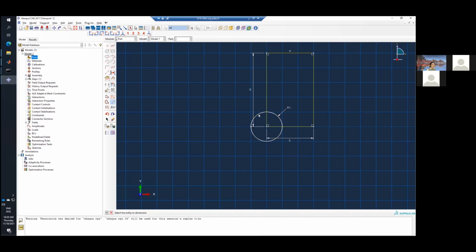And now you will see overlapping outlines with these two shapes. Then we need to delete all these unnecessary lines. So there is an icon named auto trim. Just click this one and move your mouse to the lines you want to delete. Select it, then it will disappear. Again, select this one and also these two small parts. So you will see the geometry like this. And you see your dimension is also deleted with that one. If you want to see it again, you can add it again to this small part of the circle. So this will be your final geometry drawing.